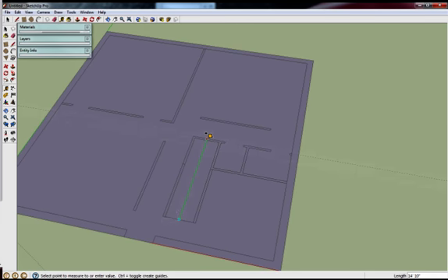Start by measuring the stair opening and dividing that by the number of stairs desired. I want 15 stairs, but the top stair is actually the top floor, so I divide the length by 14. Move the line by the calculated distance, here 1 foot. Then type X and the number of stairs you need, here 14, so it creates the steps without repetitively moving the line manually.